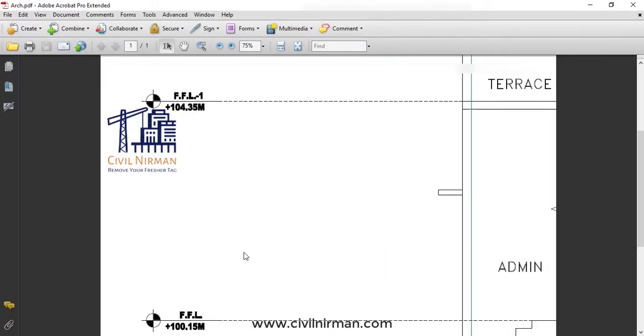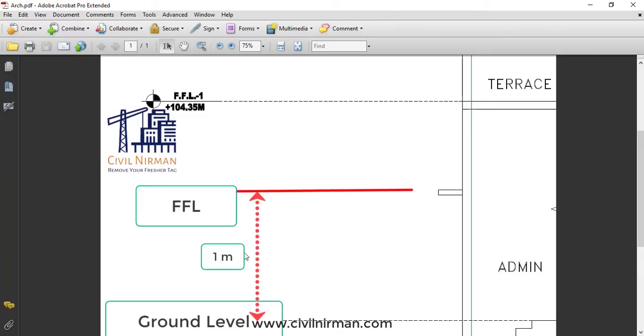Let's say you are designing a ground floor of a building with a concrete slab as the structural foundation. Now the ground floor is going to have rooms with various types of flooring materials. It can be wood or regular tile flooring. Let's say you plan to have a finished floor level of 1 meter above the ground level. That means the floor surface of the final flooring material, like tiles or wood in the rooms, will be positioned at 1 meter above the ground level.